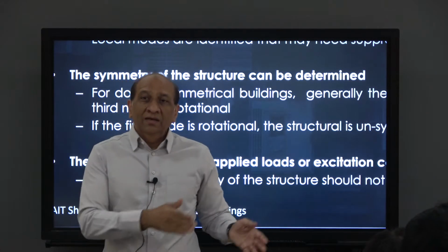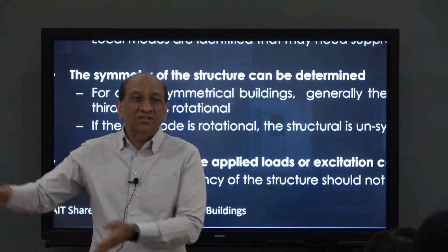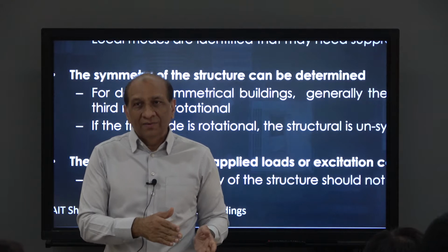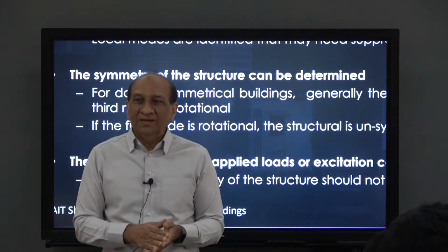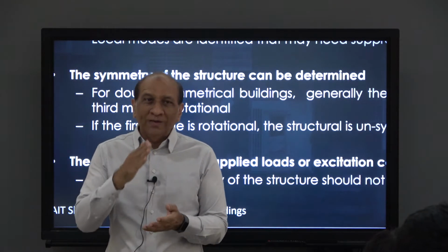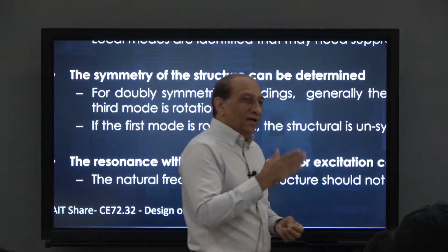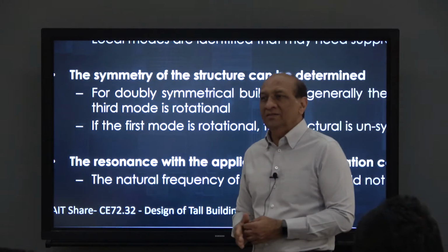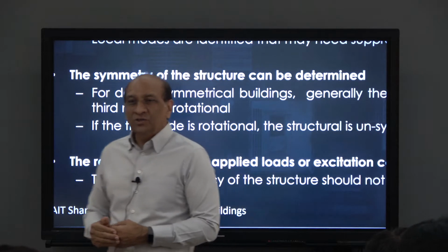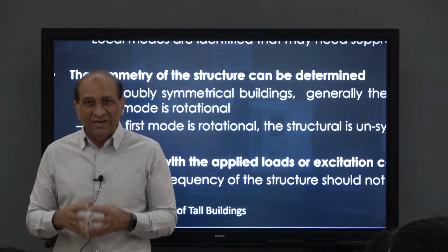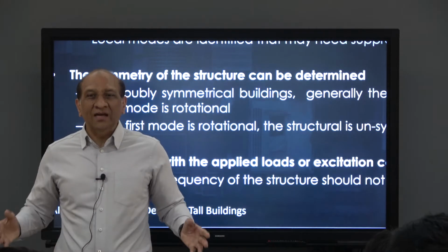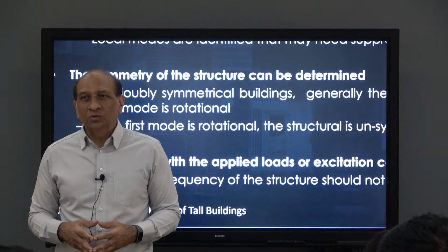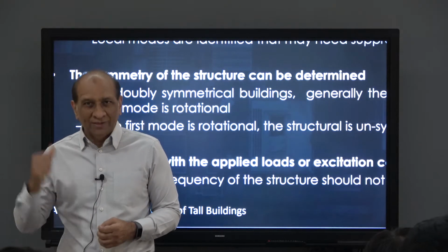So this will not change the period, but it will change the displacement of the structure. You can change the displacement of a structure by synchronizing your force application with the natural frequency of the structure and create displacements 10 times larger than what you could otherwise create due to resonance.